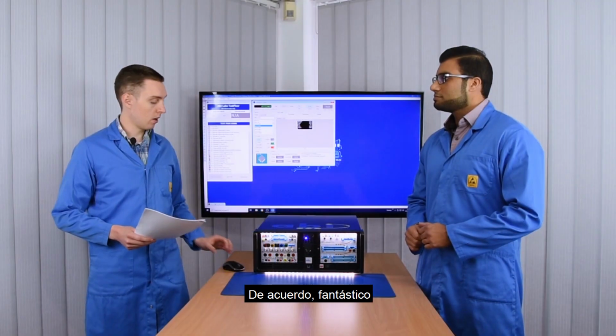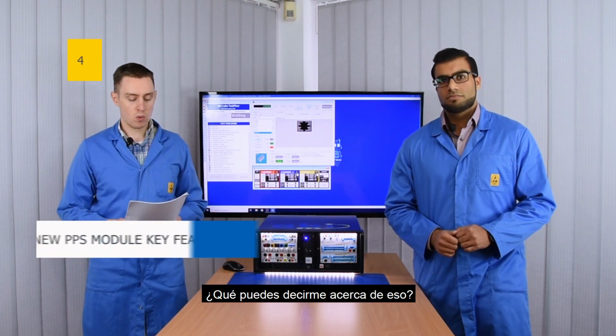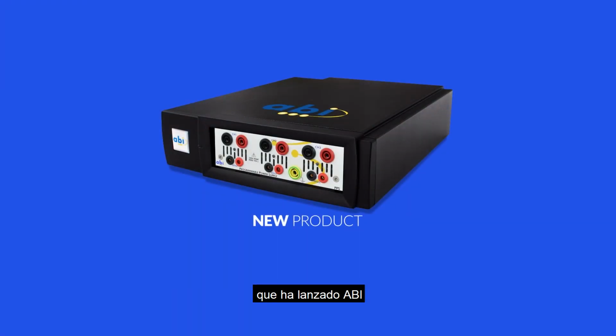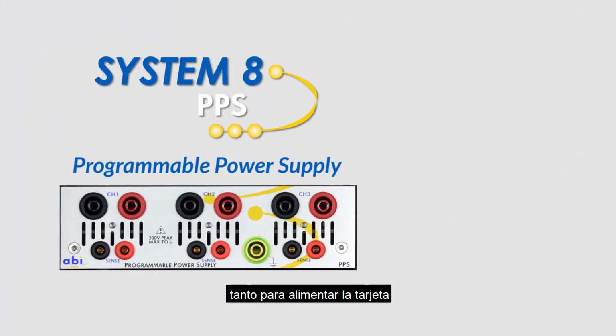Okay, fantastic. So, in episode 3, we introduced ABI's brand new module, the PPS. What can you tell me about that? Okay, as you said, the PPS is the latest module that ABI has released. And this module is the programmable power supply. So it has 3 independent channels that can be used to power up your board. And all these channels can output a maximum of 120 watts.